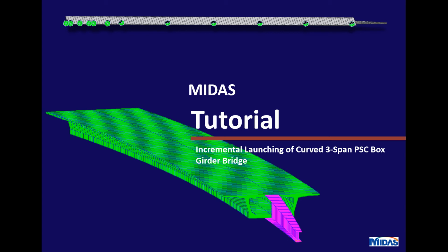Hello everyone, in this session we will learn to model and analyze a 3-span curved PSC box girder bridge constructed using the incremental launching method in Midas Civil. Preferably, ILM is used when the bridge construction involves spanning deep valleys, water crossings with steep slopes, or environmentally protected regions, etc. So ILM can offer a perfect solution to overcome these construction challenges where other construction methods fail to achieve.